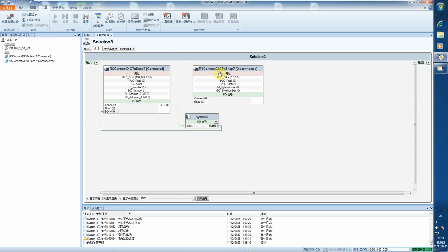We don't use the group IO; it depends on your situation and system. The input is linked to DI, which is DIO, and the output is linked to DO, which is here: M8.0, M8.3. As you can see, you just drag and link. As you can see, the changes.